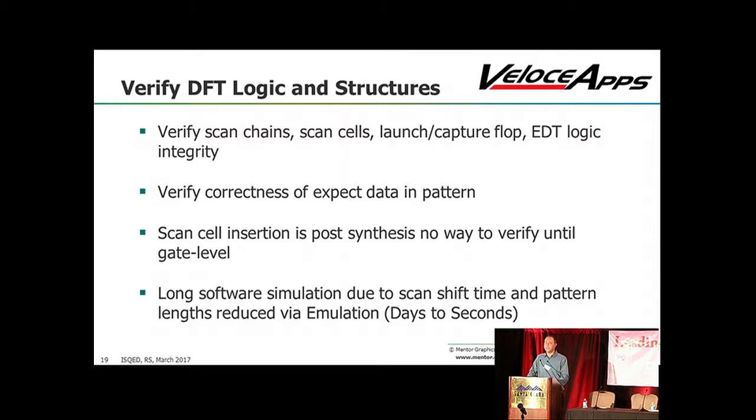Also, all of your DFT is done post-synthesis, so it's all done at gate level. Gate level usually comes later on in the design cycle. You start with RTL, you move on to gate. Then and only then can the DFT engineers actually begin their job. And that long software simulation time can get reduced, literally from days to seconds. I've got some metrics I'm going to show a little bit later, but it's literally days to seconds.